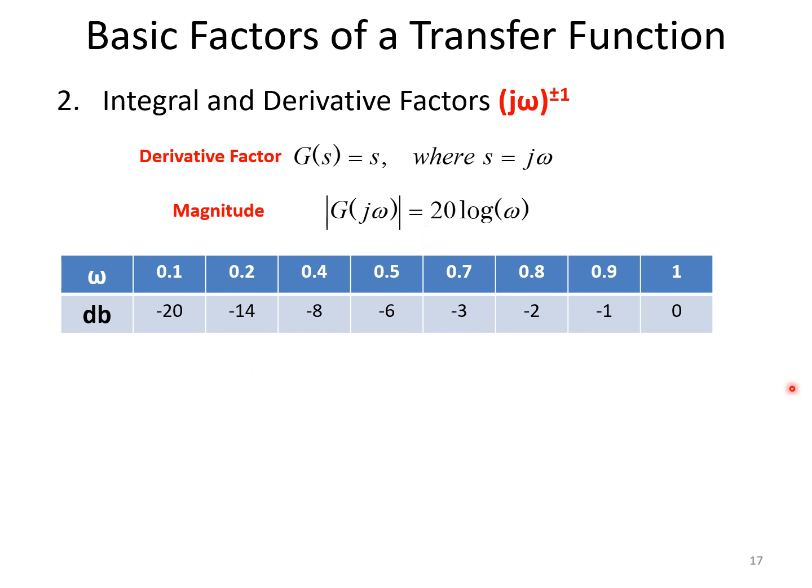Now coming to the slope, it is taken as 20 decibels per decade for a derivative factor. It is plus 20 decibels per decade because it is for one decade, from 0.1 to 1. It is taken as 0 minus (minus 20), so minus of minus 20 becomes plus 20. So the slope is considered to be 20 decibels per decade for a derivative factor. And the slope per octave is considered as 6 dB.